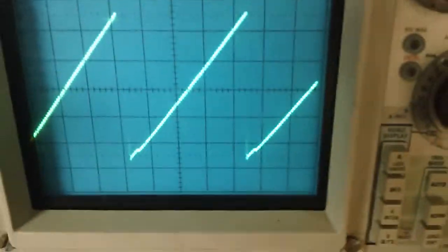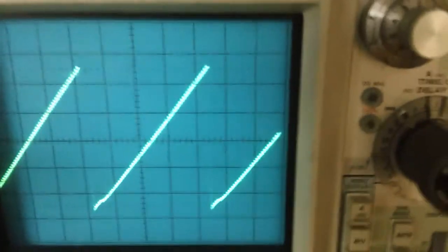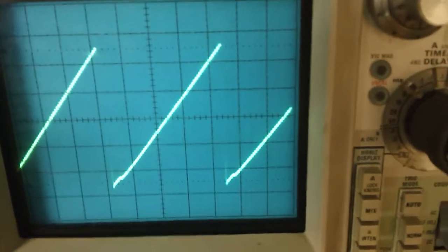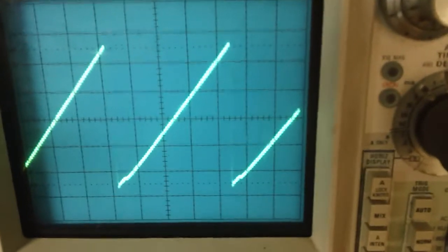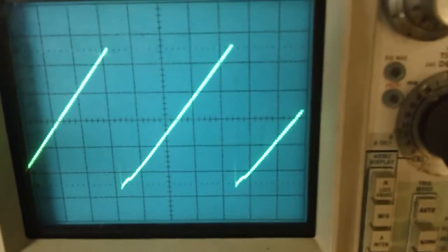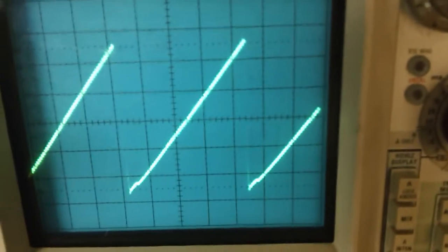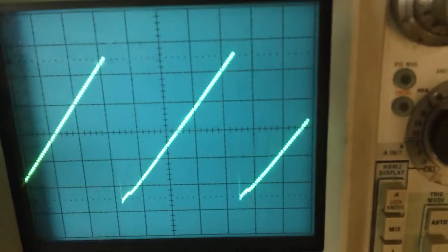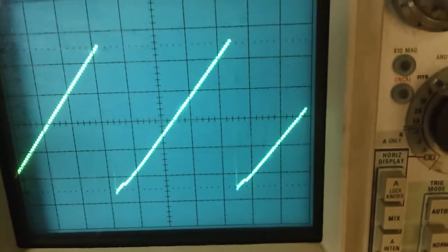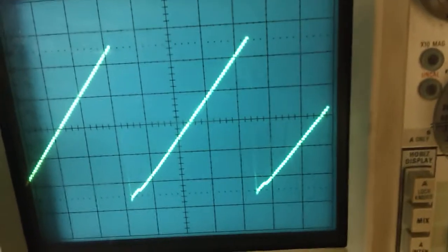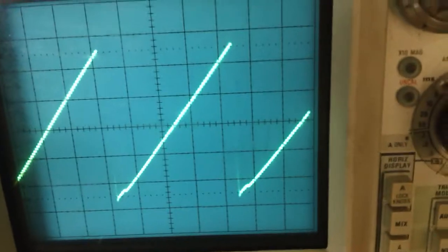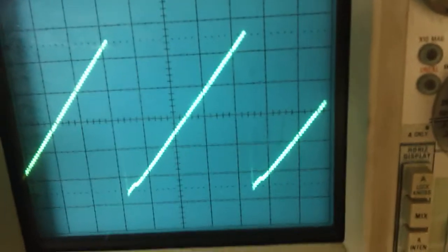Right, this ramp is a so-called trailing edge ramp. I can think of uses for those as well. For electronics guys, you're probably more familiar with seeing a ramp going this way, because it certainly was used in televisions for generating sweep, but you've probably used it in voltage-controlled oscillators for creating sweep using a varicap diode.